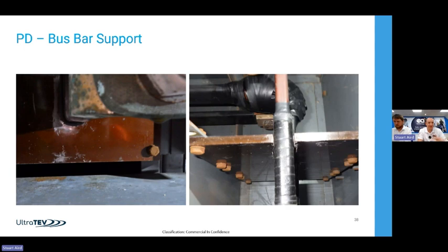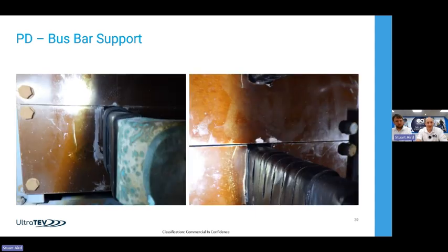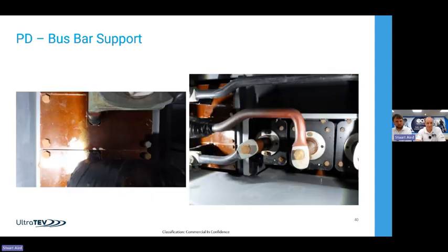And what that does is it starts to create this acidic atmosphere, similar to what we mentioned earlier. So we can see any of the nuts and bolts within there are all rusting away, and we see damage to all the supporting structure. As you can see, it's quite aged switchgear. It's been in for many years, but it's starting to fail now. And you see other ones. This verdigris, this greening again, is caused by the nitric acid on the copper work within there. And then at the little air gaps, we see little white bits and damage around there as well.